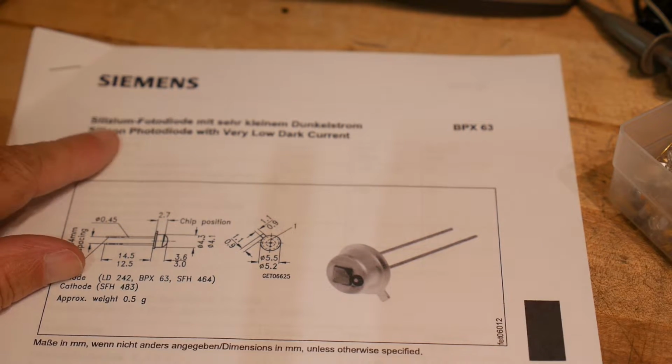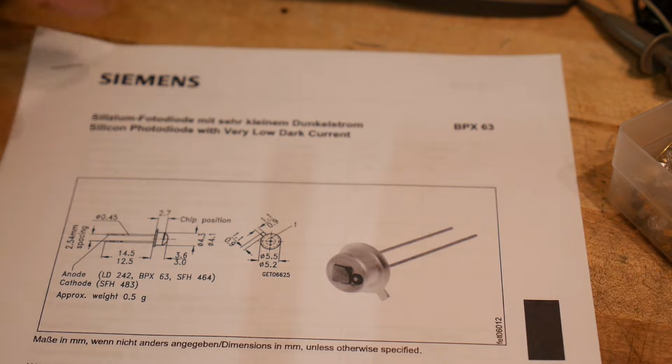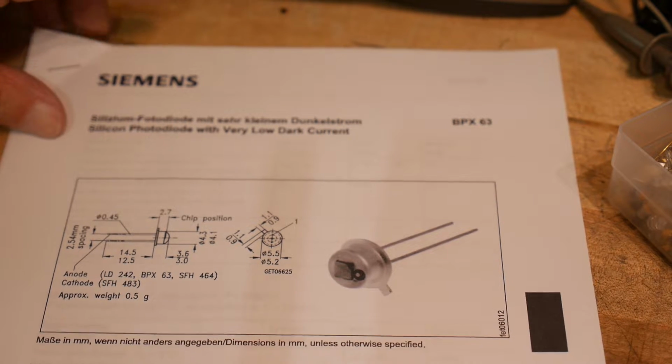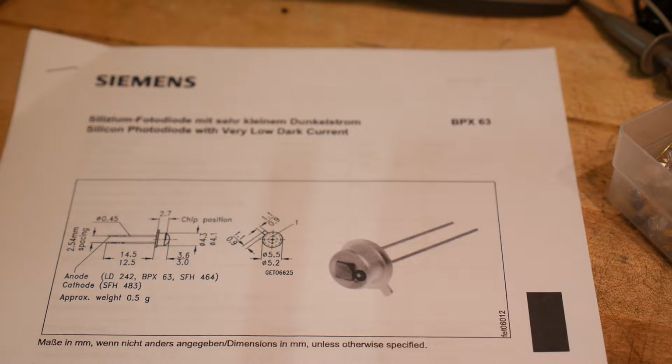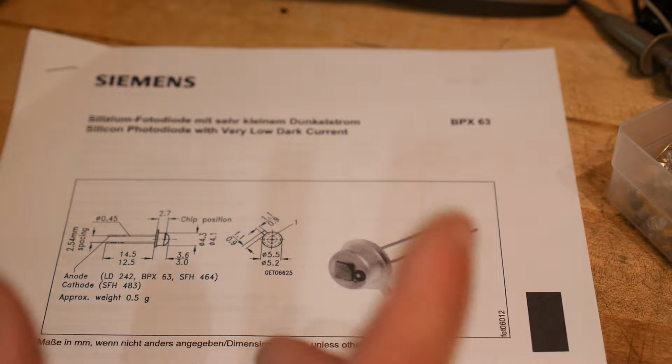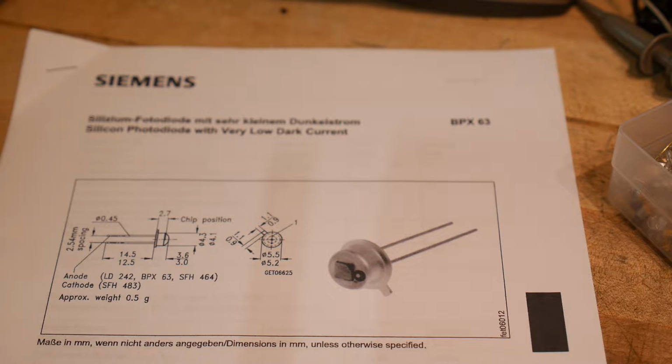Probably want to go back to the other lens. Yeah, let me change back to the other lens. All right, so this is a Siemens part, partially in Deutsch, partially in English. Says it's especially suitable for applications from 350 nanometers to 1100 nanometers. That's a very typical range for silicon photodiodes. They don't work at all wavelengths, but they work in this particular range. So same for CCDs, same for cameras and stuff. It's very difficult to have a silicon-based photoreceptor that goes past 1100 nanometers. So it can't see fiber optics, which is maybe up around 1.2, 1.6 microns.